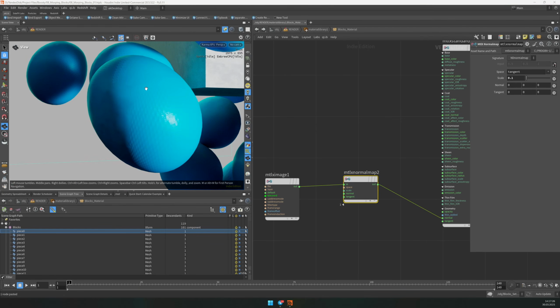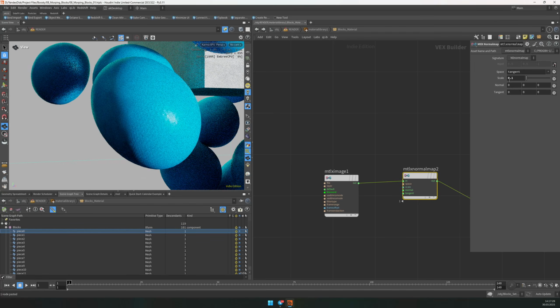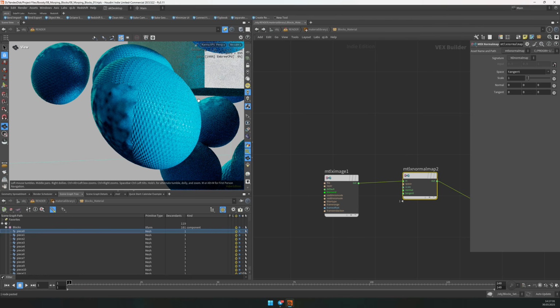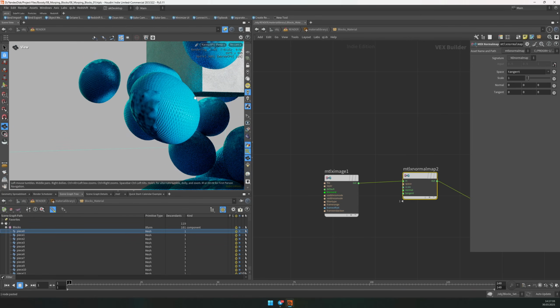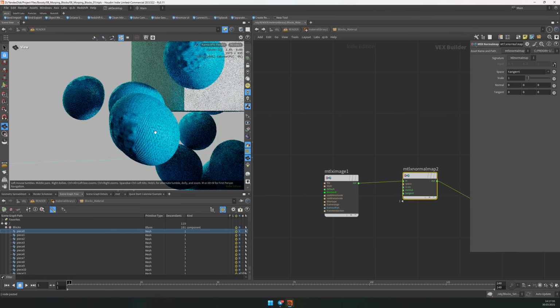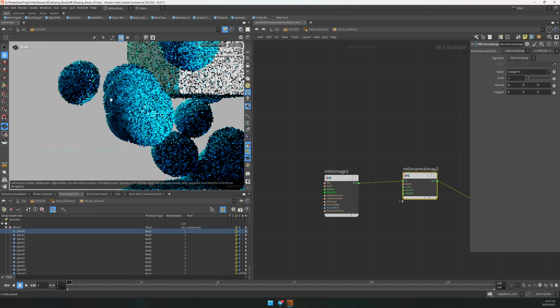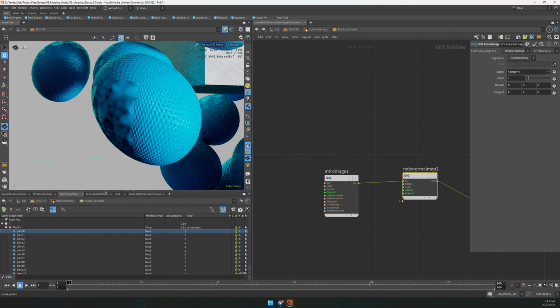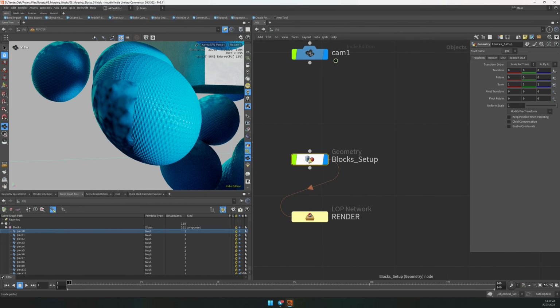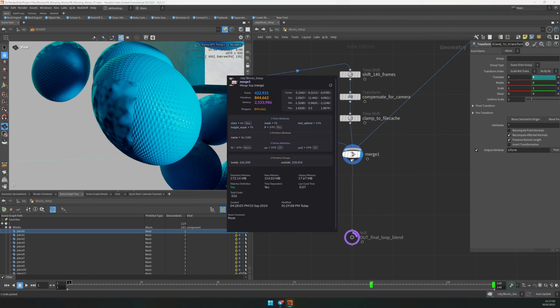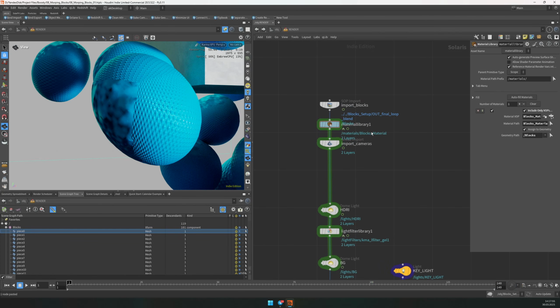As you can see, we are getting something here, but we have a different set of UVs. So in this case, this texture doesn't really fit the sphere one. So it fits the concrete right, but the spheres are not right here. And the thing is that we need to import our second UV map that we have. So we have UV and UV2. We need to import the second UV map.